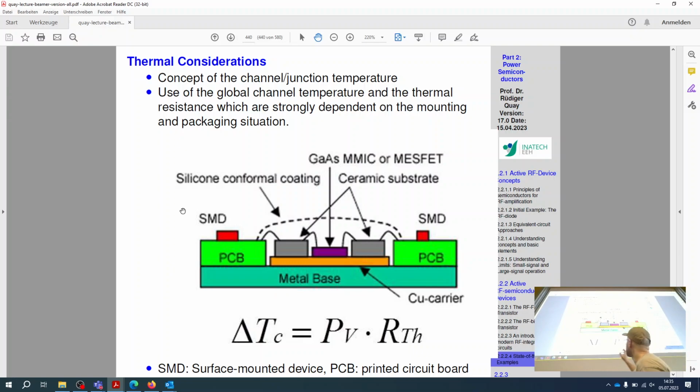That's why, in order to help the heat distribution, the device is placed in a metallic packaging frame, which is supposed to carry out the heat, and that is then mounted on a PCB, which is also metallized to have a certain heat transfer.